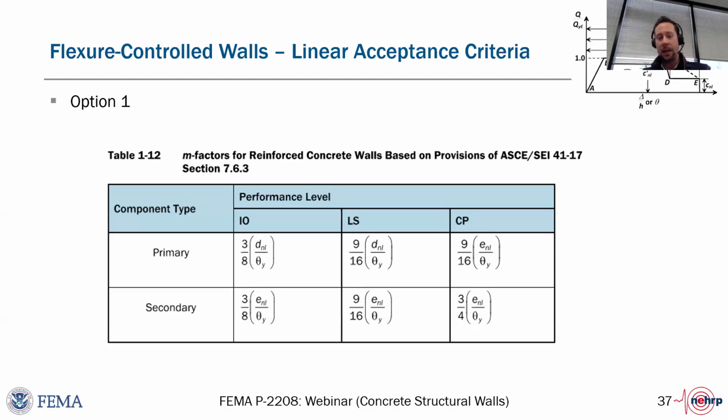The most direct way and maybe correct way is to just take those parameters that came out of the nonlinear recommendations and then apply these factors based on the rules in ASCE 41 and further some of the things in ACI 369 to then get an M factor. So you're basically backing off the acceptance criteria, one for just a little bit of conservatism relative to the coefficient of variation and dispersion, but also recognizing you're doing a less sophisticated analysis procedure when you do linear procedures. But this looks a little bit more complicated and people don't have a gut feel for what this means.